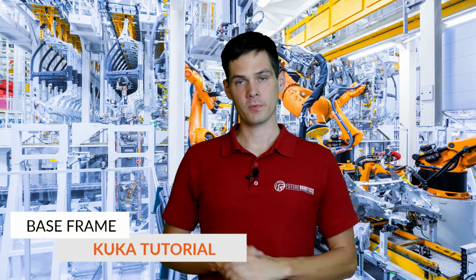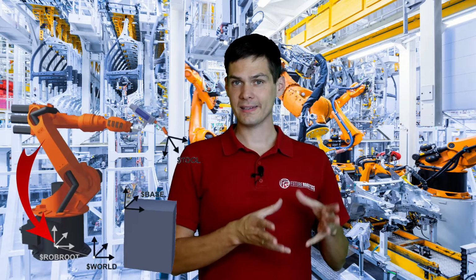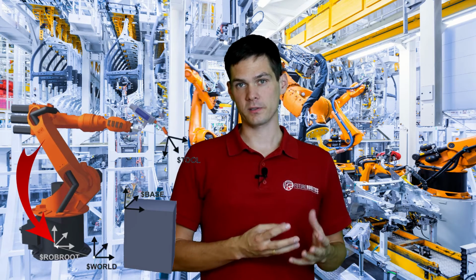Alright, so let's talk a little bit about the base frame. Remember, I spoke with you about the world coordinate system. The world coordinate system by default is located where the robot root is, and that's the base of the robot. Also the base by default, base 0, is located in the same spot.